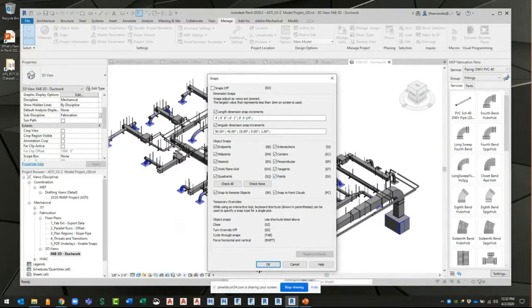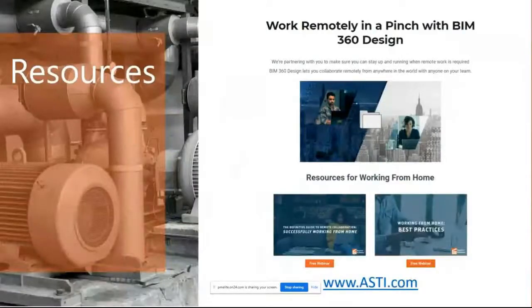Another question is, and it was from earlier in the webinar, are these export templates saved in Revit or are they saved in Fabrication? They're both. They could be used in both. So if you already have them developed in Fabrication, they should show up in your Revit projects when you load in the database. But if you develop it in Revit, like I showed you in that directory, you should be able to utilize those in CADmep.